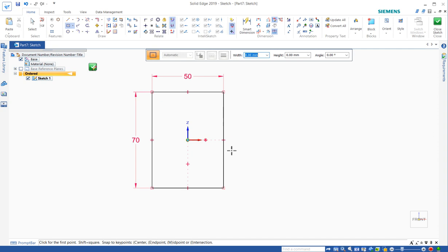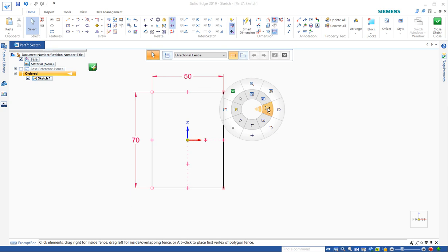So I'm going to continue, and as a result of the rectangle by center, we have some horizontal vertical relationships created here. I'll talk more about that. And notice it is black, so meaning that it's fully controlled via these horizontal and vertical constraints combined with the red driving dimensions. This geometry cannot be modified accidentally by clicking and dragging it. If I grab it by a handle, it will not move. I have to change a dimension to make an edit to it.